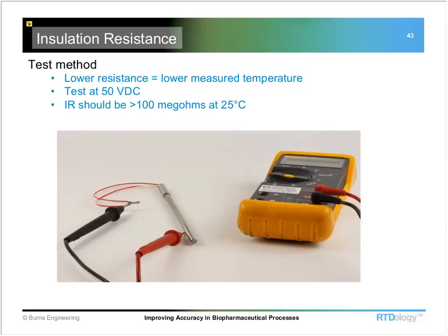Because it's a high-level resistance check, ideally you want to do it on an ESD table so that you don't have any stray voltage or static flying around, and don't be touching the part. We even do some high-level measurements here where somebody walking by with a real fuzzy jacket that's got some static in it will throw off the reading. It's that sensitive. But with this, that really wouldn't be an issue at this level.